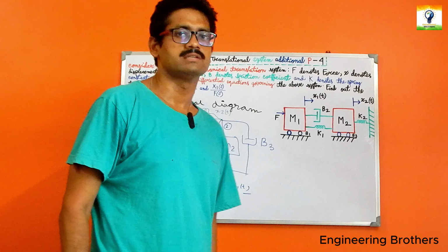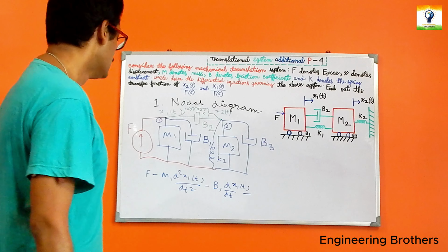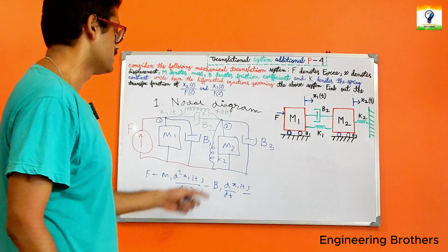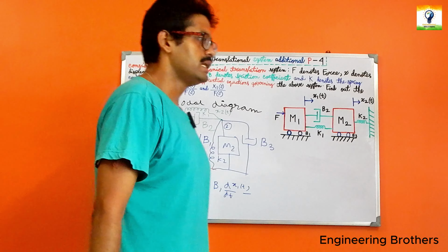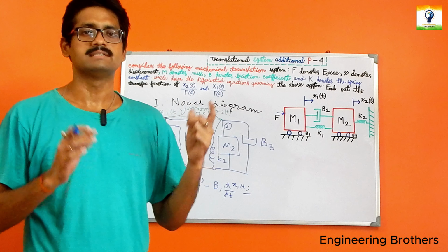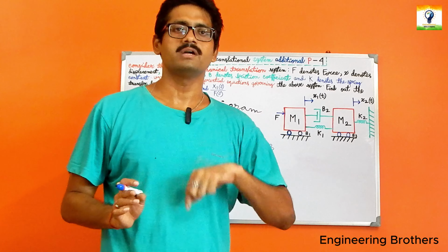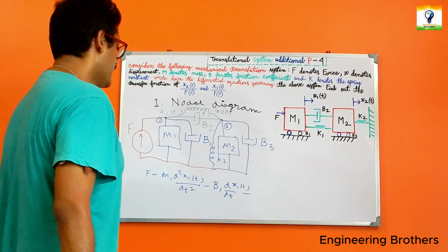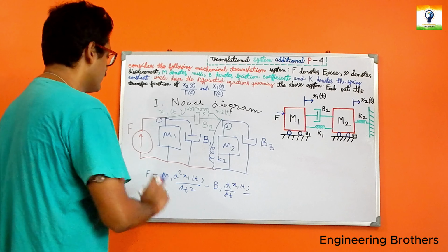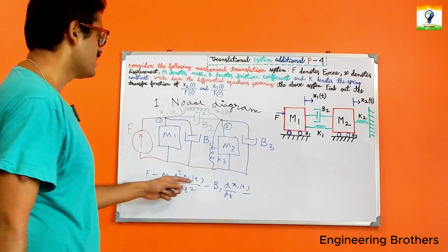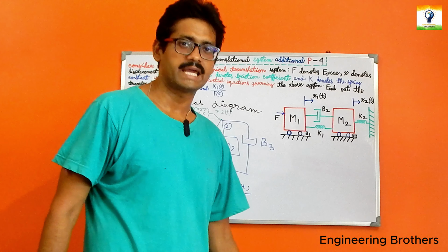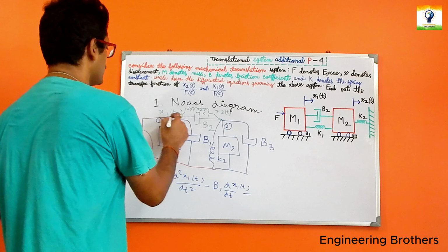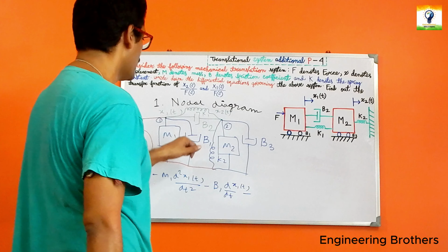Because these are our resistive force elements. So applied force plus resistive force. And why do I consider these forces as negative? Because the direction of the resistive force is opposite to the applied force. As it prevents the applied force, its direction becomes negative. So applied force minus the resistive forces of mass block M1 and then b1.